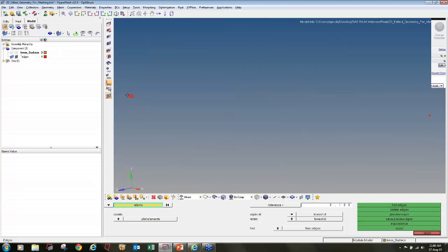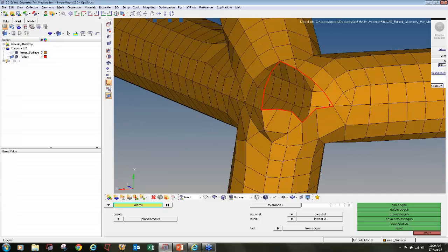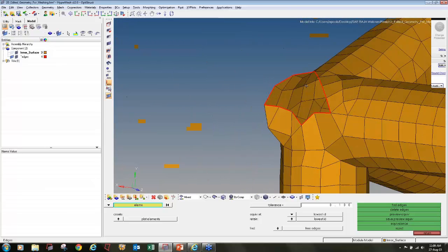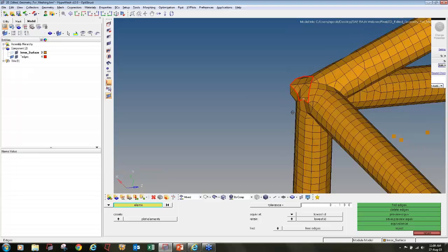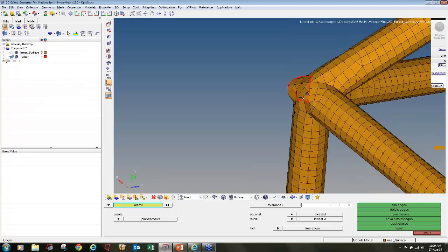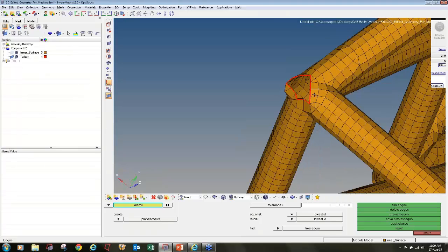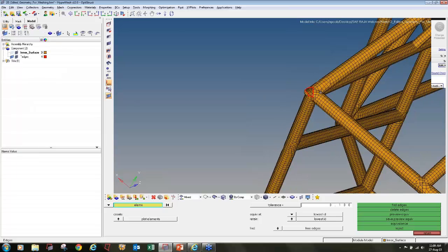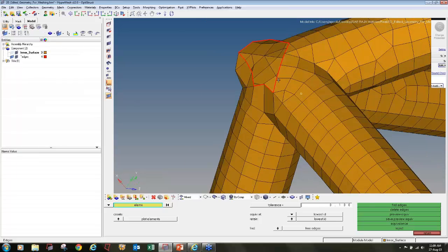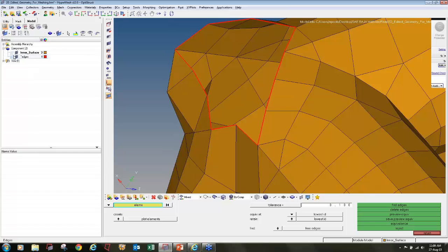This is perfectly fine because the elements are not connected here. But the other problem is this. I find one space where my meshing said one area failed to do meshing is this. Here also I find a gap. As I already told you, I don't want any gap on my roll cage. I want every element to be connected. So I will see why this gap comes.